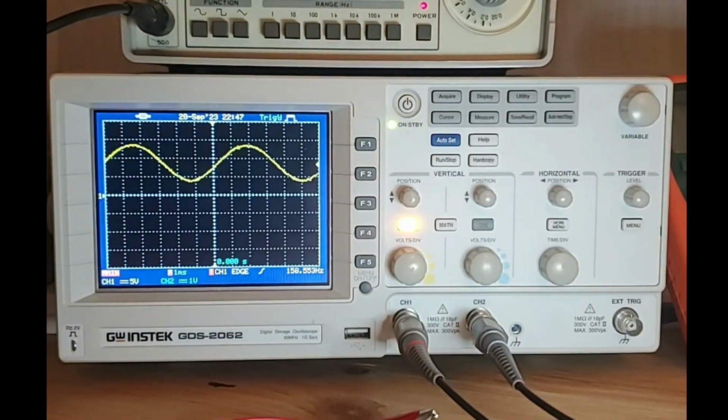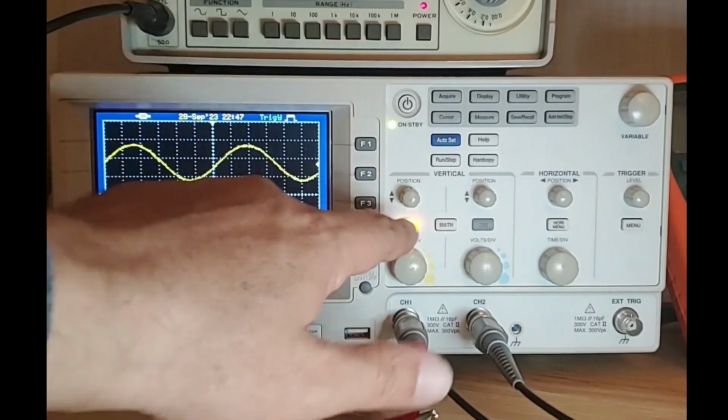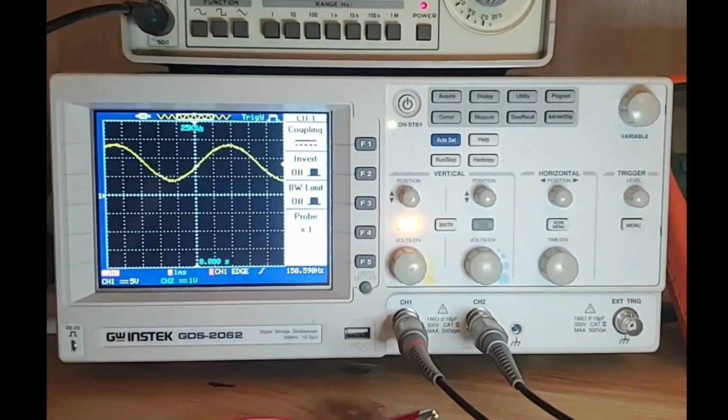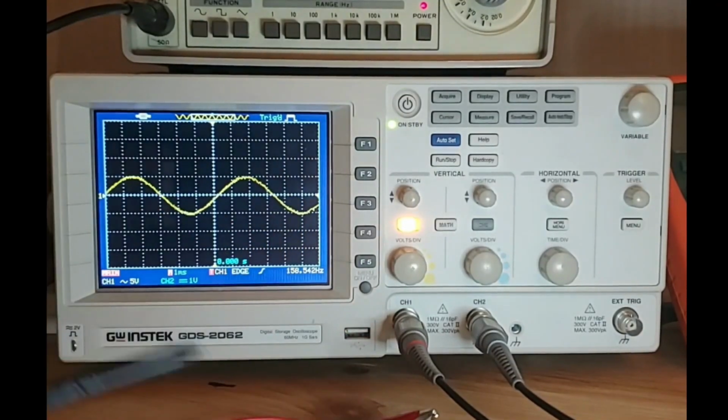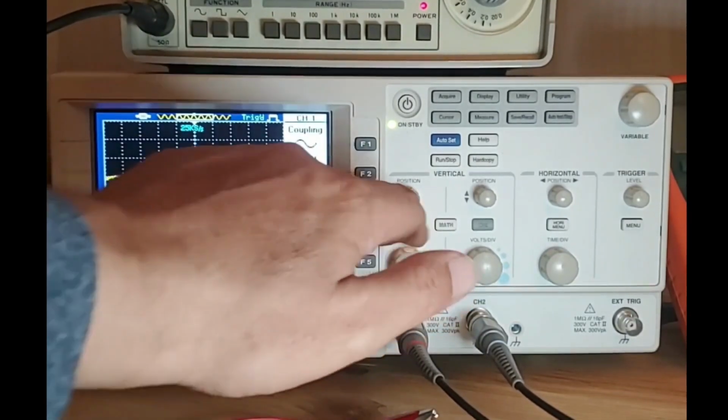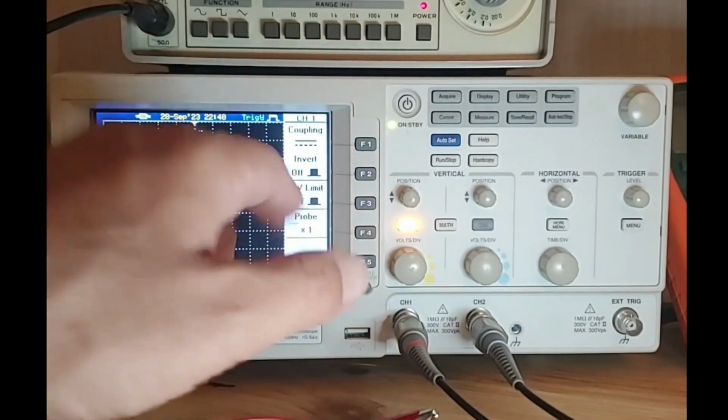And this is what a DC coupling will show me. It will show both the DC part and the AC part. If I'm not interested in the DC part and I want to remove that part, then what we can do is press channel 1 again, go to the coupling and make it AC. So you can now see that this is AC coupled. And now you see what the probe has done: it has removed the DC part from the signal and it shows me only the AC part, which is the part that is changing with time. So the AC coupling can remove the DC part of the signal that you don't want to see. I will go back to the DC coupling. This is the original waveform.